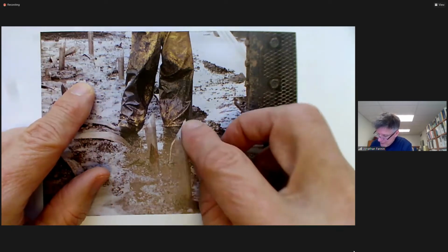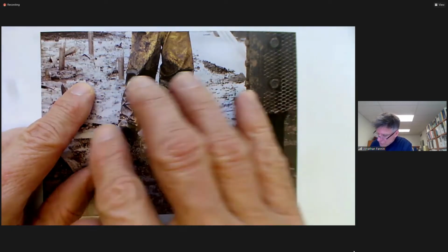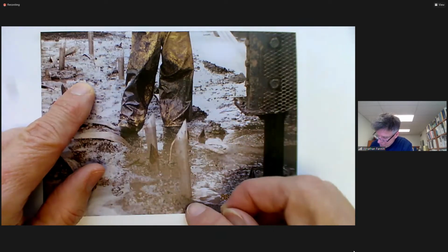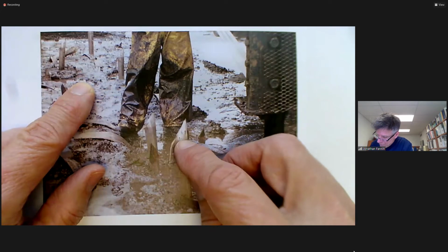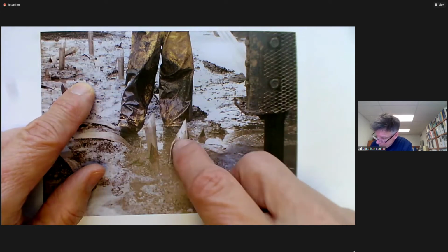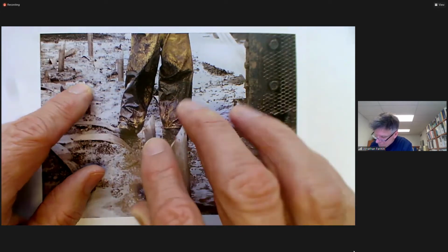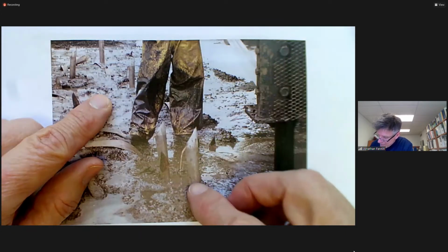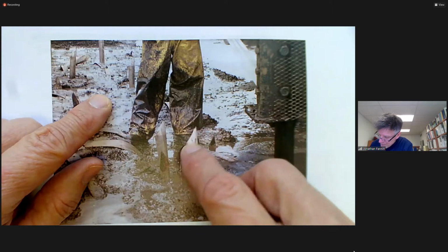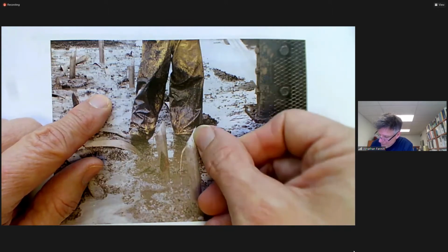Can you see here? Look, there's no surcharge load or anything, but even just the self-weight consolidation has driven the pore fluid up, and it's actually spilling over. You can see it again over here. There's standing fluid inside the sheath of the prefabricated vertical drain.